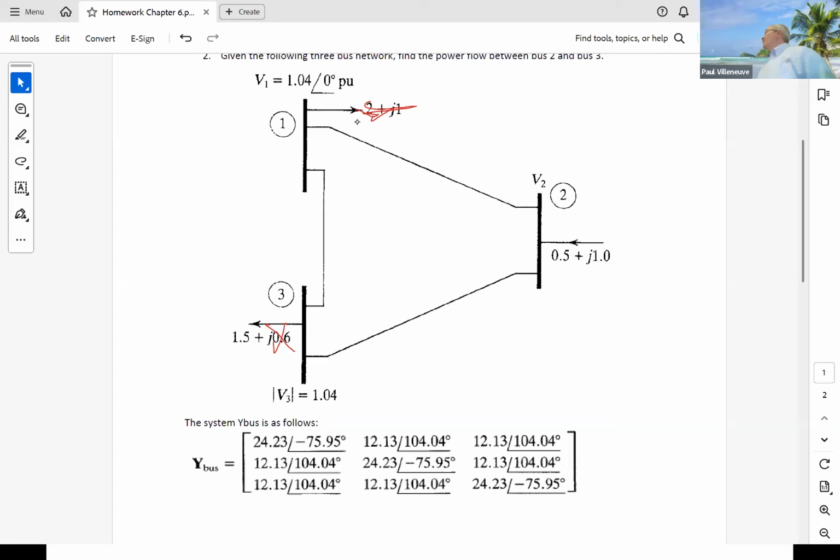So this is going to have 3 equations. Your Jacobian is going to be 9 by 9, and your G terms don't go away. Now it seems as if you prioritize the slack bus first, because you could have said, fine, this is the load bus, if that voltage goes away. Well, you're sort of right.